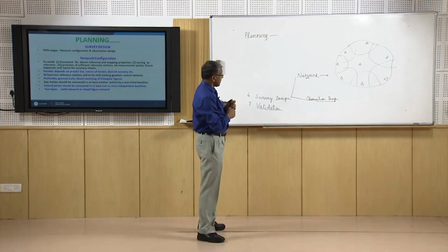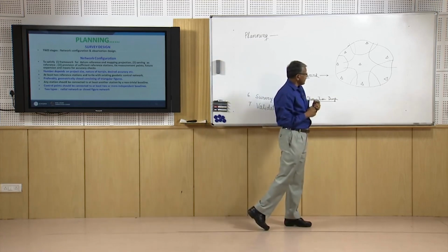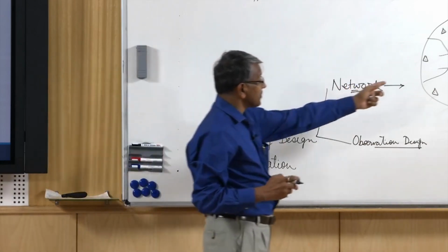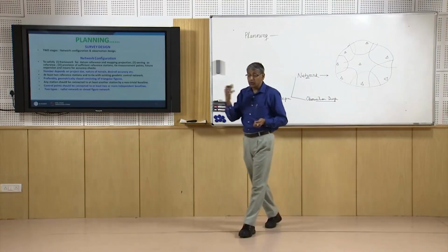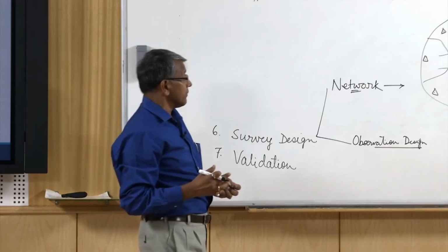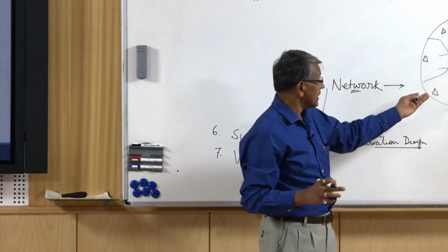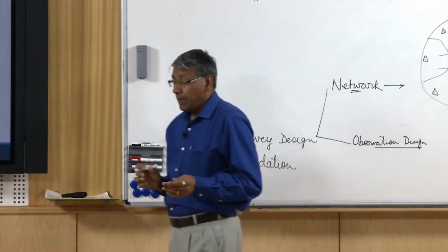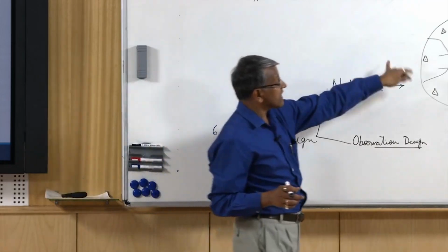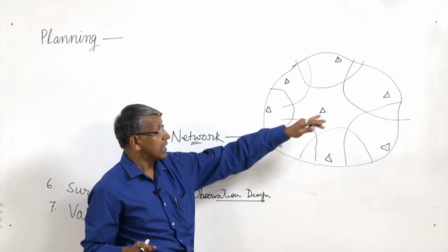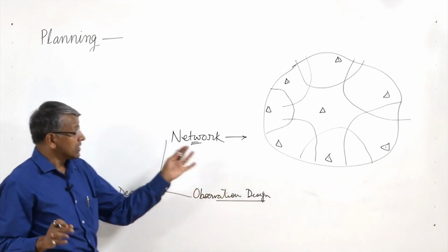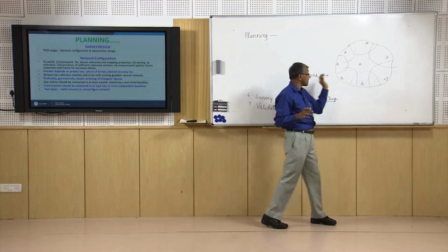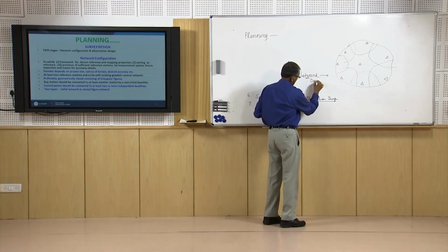Now another point which is important, not only the number, but these stations should be tied to the national surveying network so that we can have the local network system, and also it should be designed in such a way that in future we may extend our network. So these are the primary points which we should keep in mind during the network design.